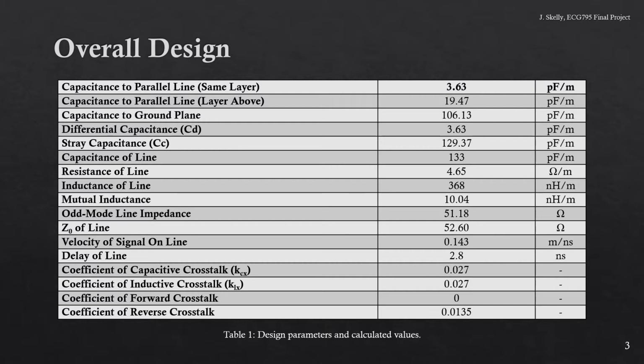Since the design uses bipolar differential signaling, the line impedance can be characterized by the odd mode impedance alone.